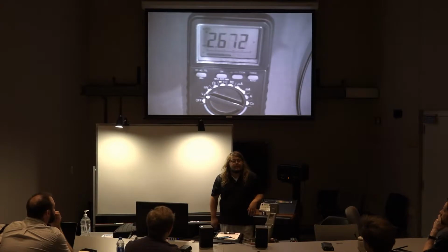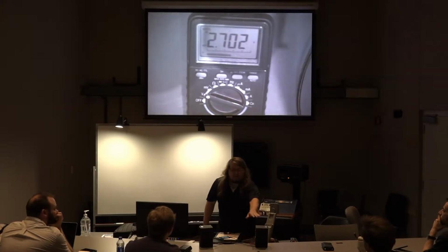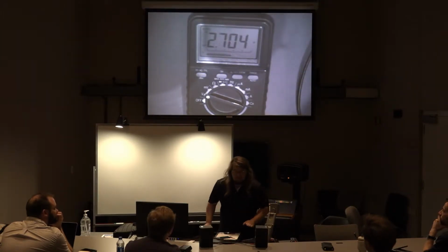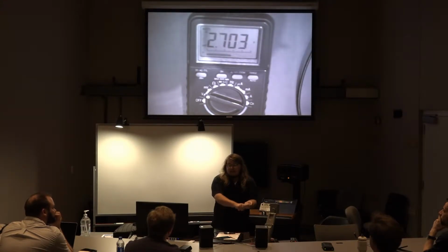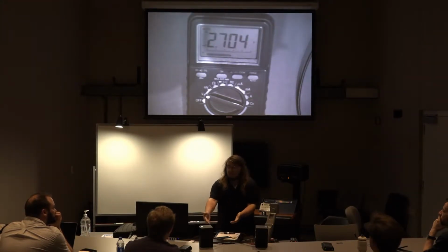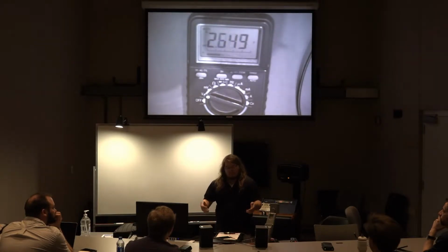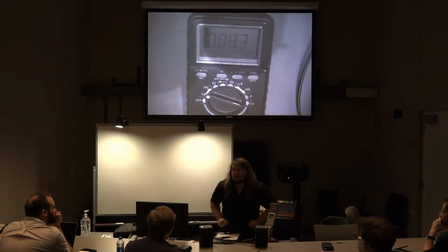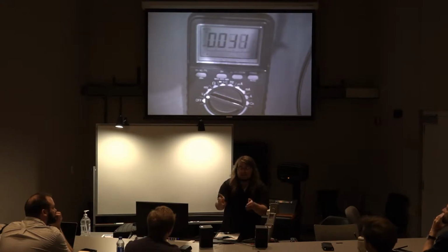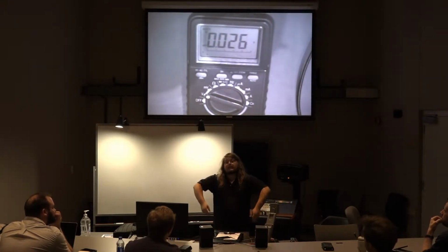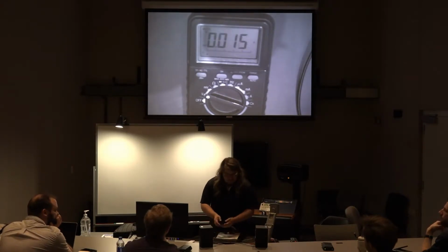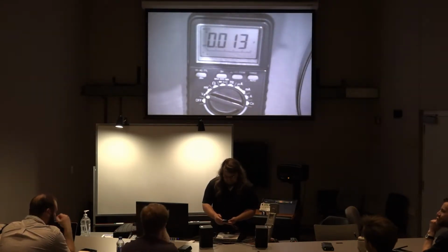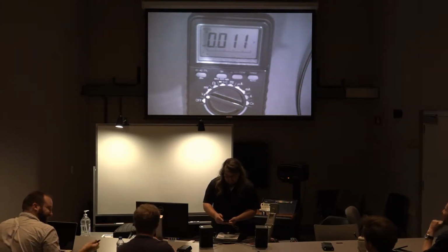Our whole voltage, right? The same voltage that we just had applied before. So what's happening is we're indeed splitting the output voltage. The power amp output has remained the same. The input voltage stayed constant. The gain stayed constant. So the output voltage was constant, right? But then we added another speaker in series. So we'll come to find out here in a second, the voltage split across the 2. Okay. That's pretty cool.